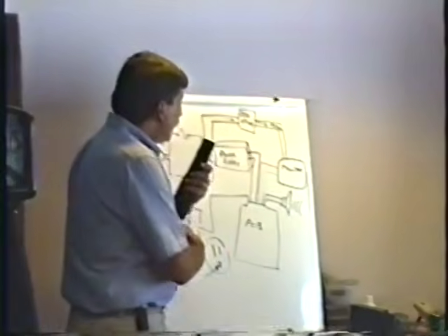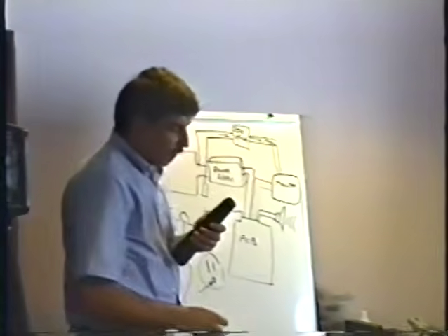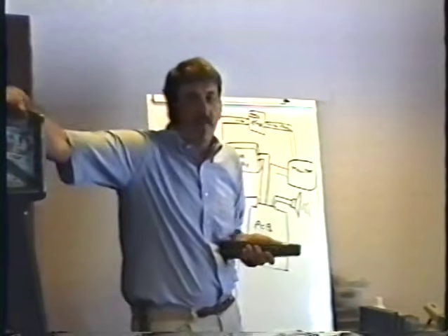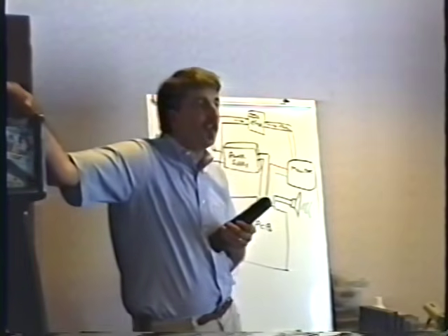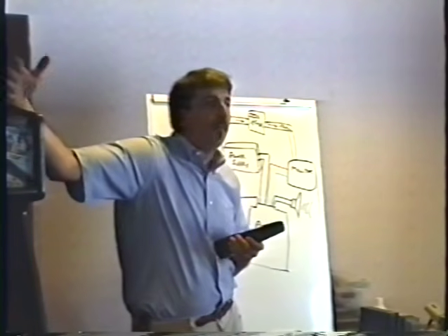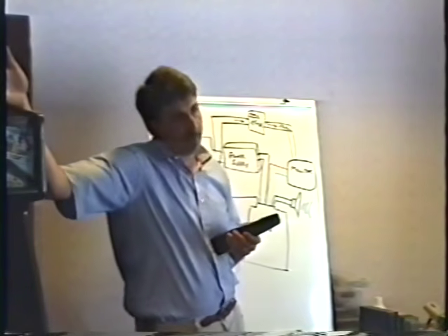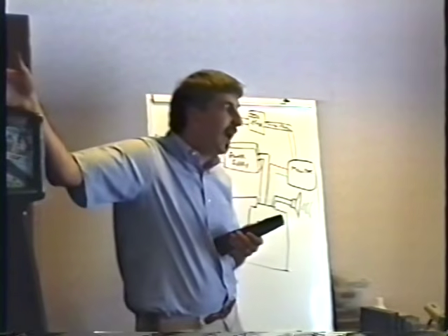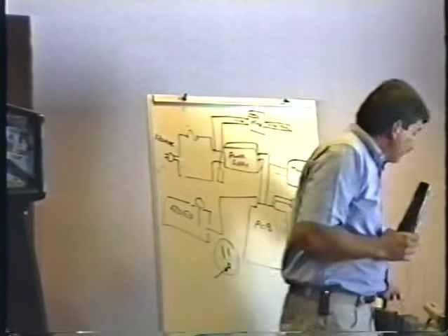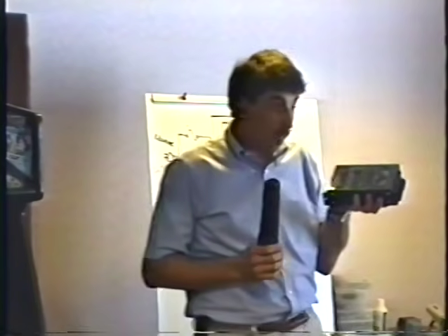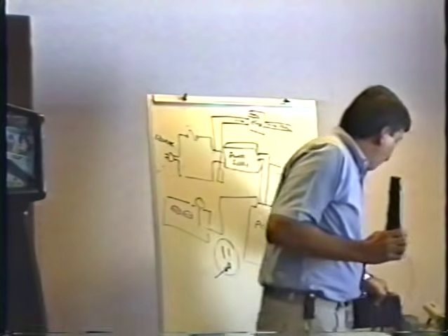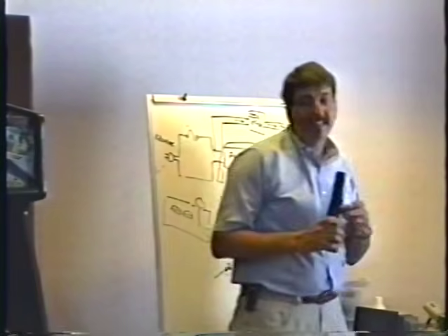Make sense? Now, one common problem that we have a lot is the 5-volt power supply just goes out of adjustment. After a period of months or years with temperature changes and changes in component values, the output voltage of the power supply may drop. It probably will drop. It's really important that that 5 volts be exactly perfect.